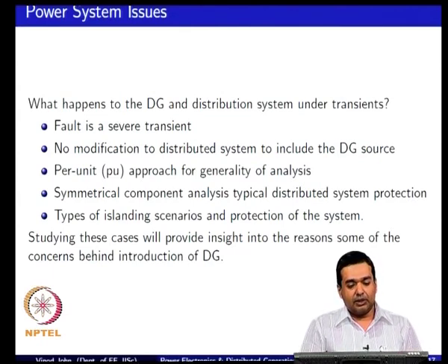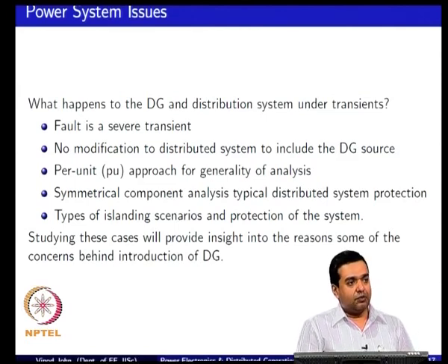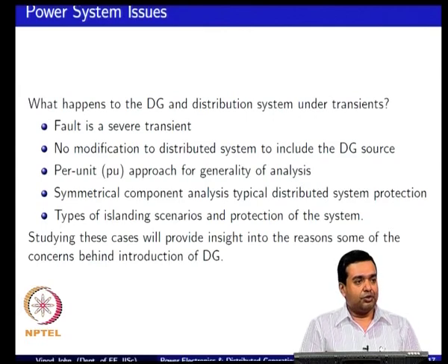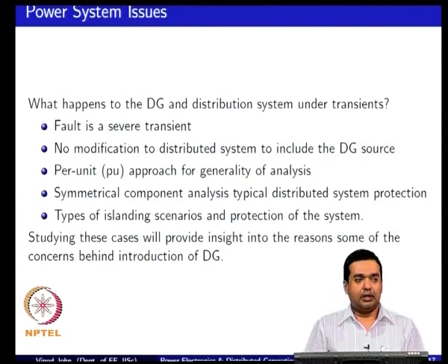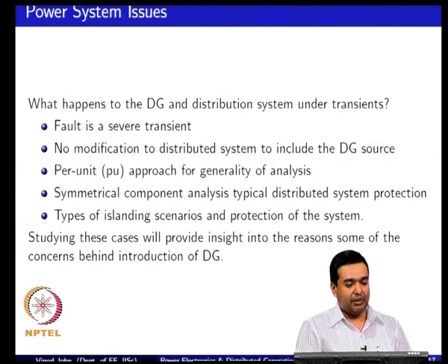Some of the background that you would use when you look at, say for example, fault studies is you would typically do a per unit analysis to actually evaluate what the fault levels are, what the voltages and currents in the system are. So, this would be something that you would have from your power systems background.